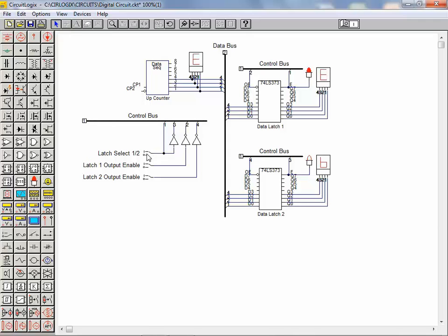In addition to indicators and hex displays, digital states can also be illustrated using the tracer button. When this button is selected, the digital state present on every wire in the circuit is illustrated by a color change. A color change to red indicates a digital 1 present on that wire. The wire reverts to its original color when a digital 0 is present. With the simulation stopped, we can now click on the Reset button to clear all the digital values present in the circuit. We'll now move on and illustrate how digital waveforms can be displayed while running digital simulations.